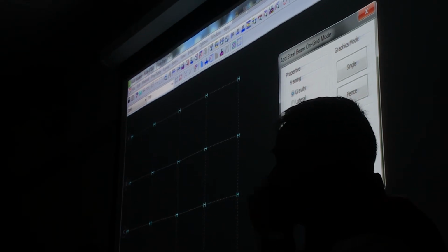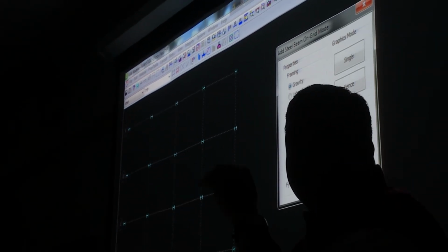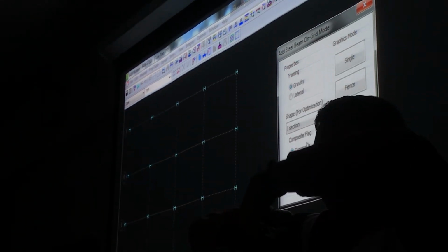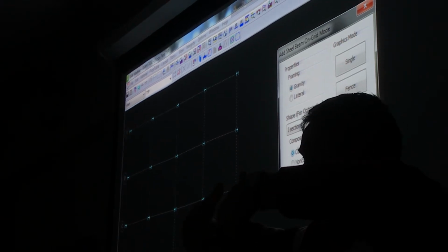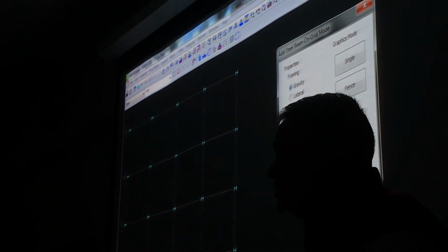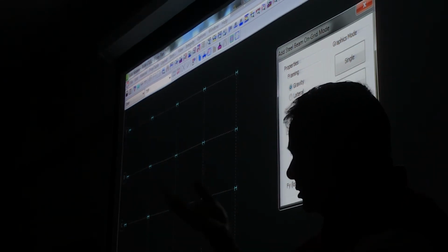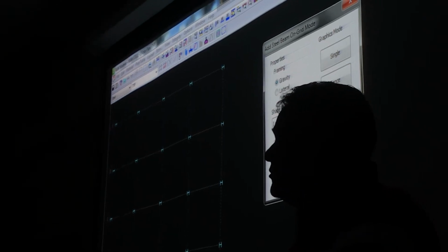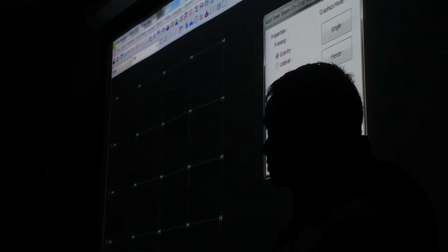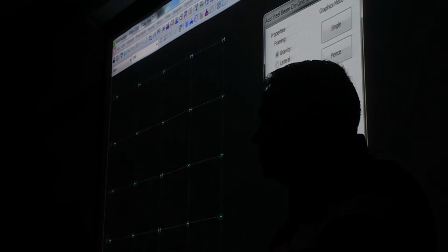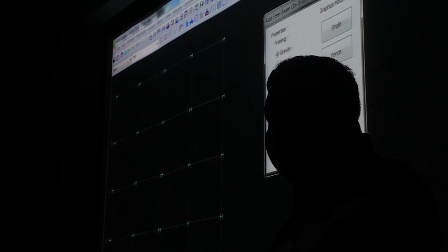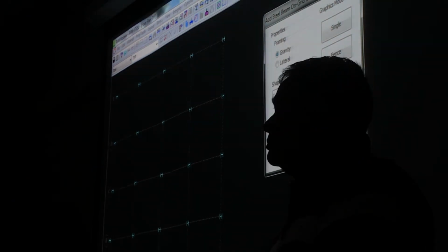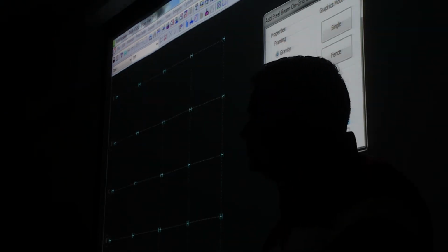Composite sections are like when you have a deck on the top of the beam, and the deck carries concrete, and if there is a bending, positive bending on the beam, that means top part is in compression and bottom part is in tension. And the top part of the beam has a deck which carries concrete, and the advantage for concrete is that it can take a lot of compression. So if we are providing concrete on top of the steel beam and it is in compression, why don't we take the advantage of concrete being there, take the compression?